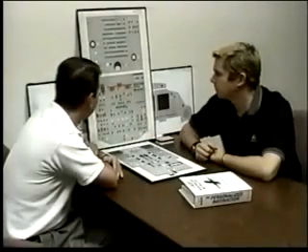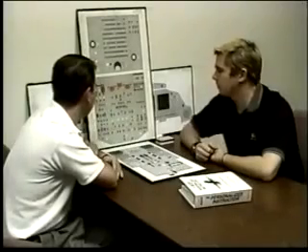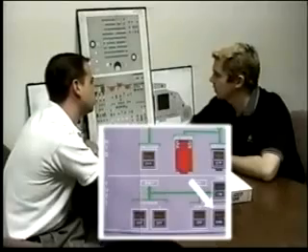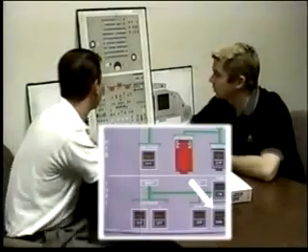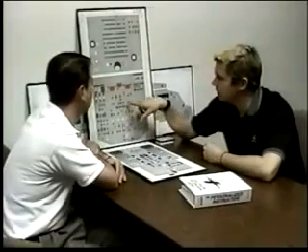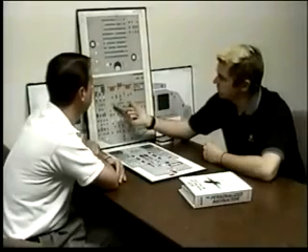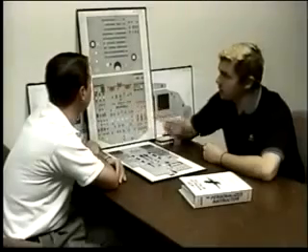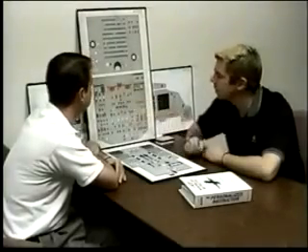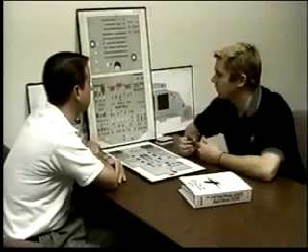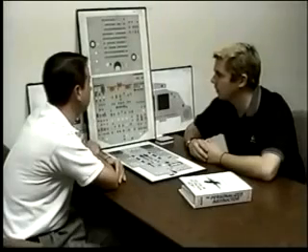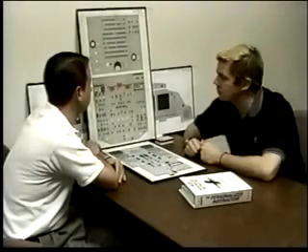Walk me through a loft scenario in which we have fuel in all the tanks, all the switches are in, and the mode select is in auto. Okay. Starting with pushback. Full tanks is going to be 43,000 pounds. And we know that that's going to be 14, 15, and 14. So with 14 and 14, that's 28. Anytime I have more than 28,000 pounds, I'm going to have fuel in the center tanks. So I push back and I start the engines. The center tank pumps are going to run for 2 minutes after engine starts, regardless of the slat position.